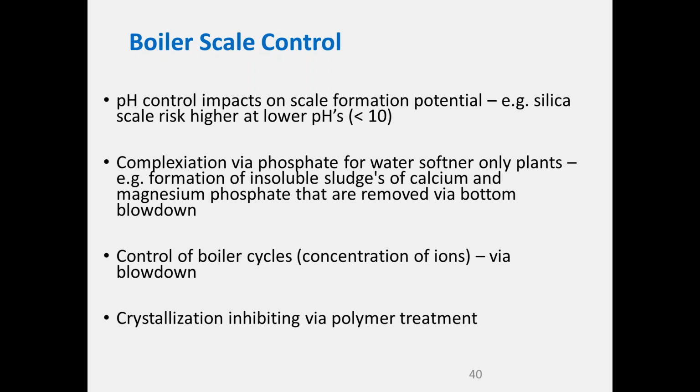If anyone's ever dealt with silica, once it precipitates, it's very difficult to remove from a surface because basically it forms a quartz-like deposit. You've either got to mechanically remove it, or you can't dissolve it off with most normal acids. Hydrochloric acid won't touch it, citric acid won't touch it. The only acid that will pick it up is hydrofluoric acid, which has particular health and safety handling considerations. If you're not comfortable with hydrofluoric acid, you don't really want to be using it. So you want to avoid silica precipitation if you can.